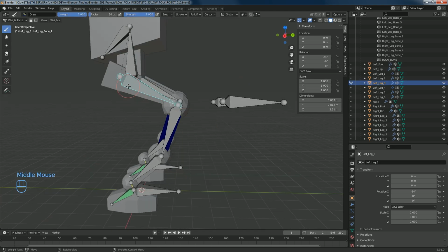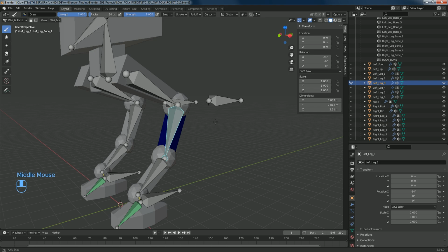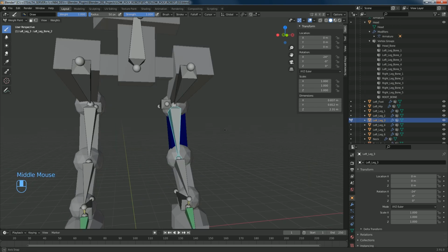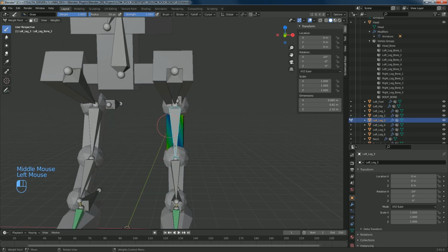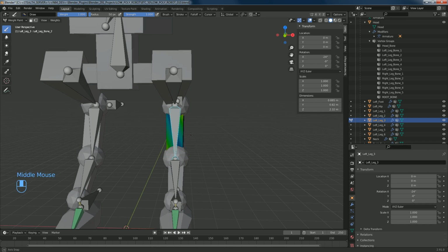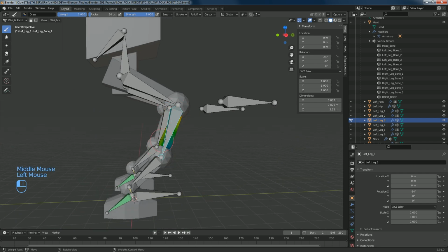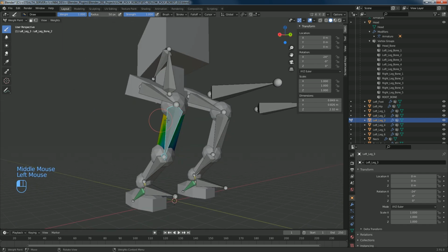Now we're going to make sure that we have the left leg bone 2 selected. So we'll deselect all the bones here, and we'll only select this left leg bone 2. And now we'll paint that. And again, if you're having issues painting and it's not going to the red color, you just have to hide the 2 objects that are adjacent to it on the list here.